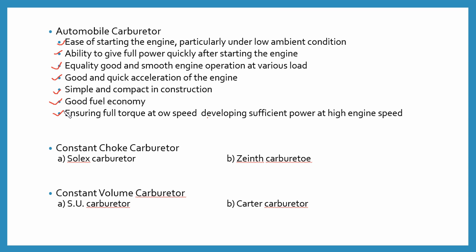So students, from here we get a common question: why do we use a carburetor in an automobile? The reasons are: first, it eases the starting of the engine, particularly under low ambient conditions. Second, it is able to give full power quickly after starting the engine.